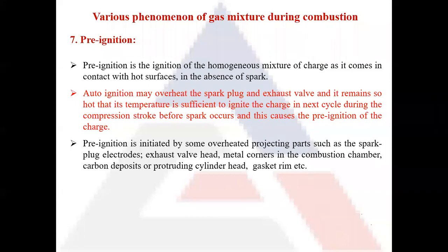So again, this pre-ignition is the cause of detonation or knocking inside an IC engine. Pre-ignition is initiated by overheated projecting parts such as spark plug electrodes, the exhaust valve head, metal corners in the combustion chamber, carbon deposits, or a protruding cylinder head or gasket rim inside the combustion chamber.